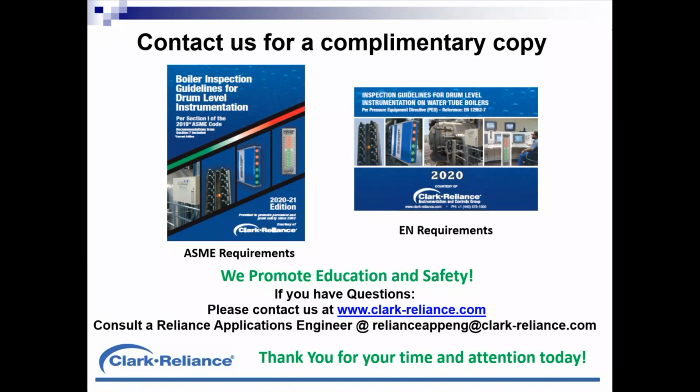Yes, that would be permissible. There's nothing in the code that would prohibit someone from using all of the same technology for remote level indication, just that you have 2 of them. And my comment or suggestion was, if you have multiple technologies, they can't fail in the same manner. So you eliminate a risk for common mode failure, but that is permissible.